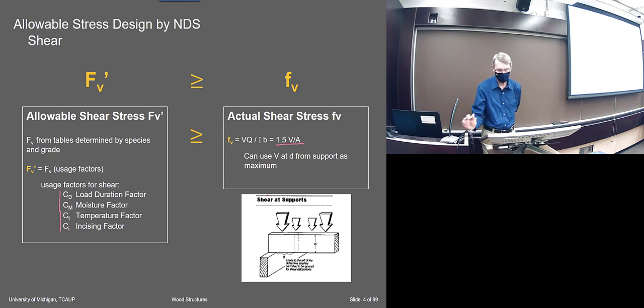And I don't know if we mentioned it already, but the critical distance for shear is actually at d distance away. It's not really the max. V max would be at the reaction, right? That would be the support, basically. Would be the maximum shear.